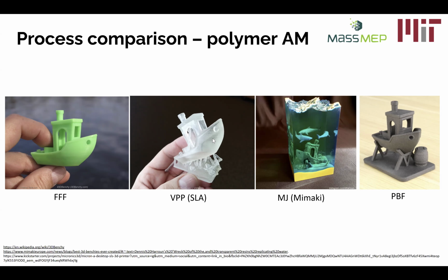We also see a clear material, which is traditionally difficult to do in thermoplastics extrusion, especially because the layer lines create problems, even if your material is totally transparent. But if you want clear components, now maybe not optically clear, which has a special meaning, but generally clear to the layman, then photopolymerization can be a great option.